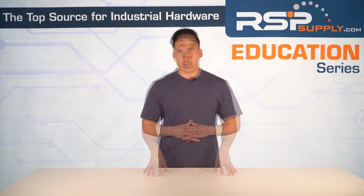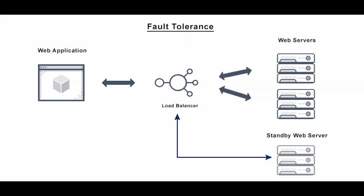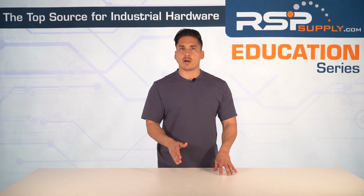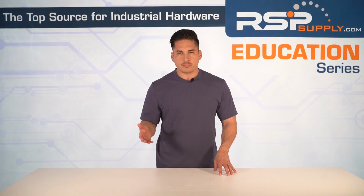Redundancy and fault tolerance. In automation, redundancy means backup systems. Fault tolerance means your systems keep running even if something fails. For example, dual PLCs or redundant Ethernet paths in a water treatment plant with the SCADA system help prevent downtime.